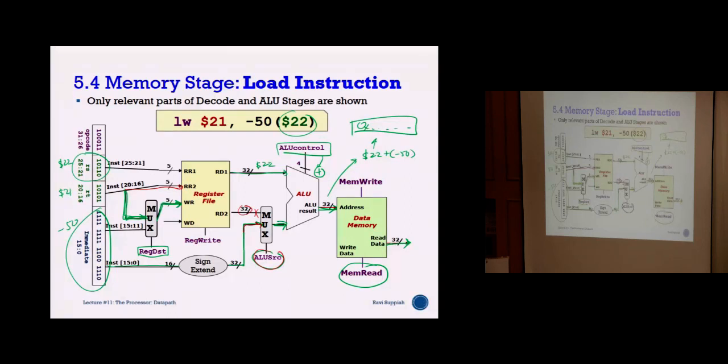Yeah, the value is still there, but we are going to ignore it, not discard it. Not for now, unless it's store word, then it's sent to write data in the data memory. So you must think of it this way: the data is traveling everywhere all the time. Then I must have my correct control bit to decide which data I'm interested in, and where the interested data should go. So all the purple text words are the control bits.